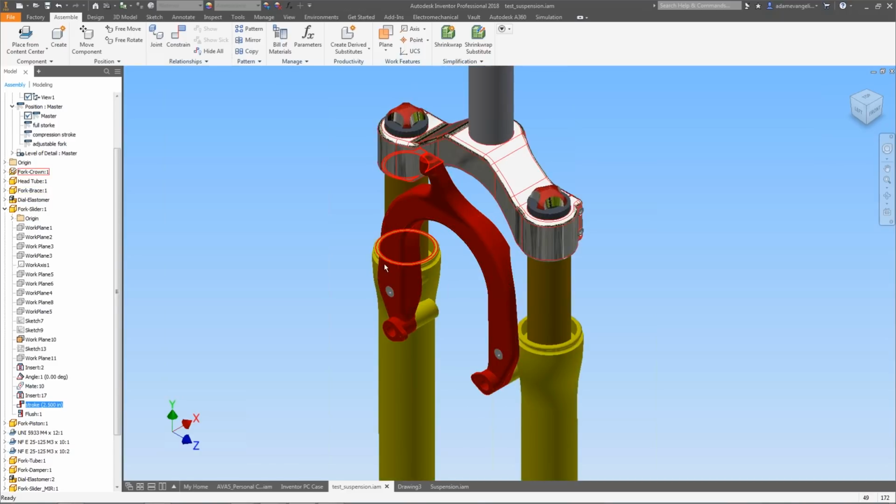If you see these red circles over here, this is the constraint that we're concerned with. By default, in the master representation, that constraint is set to 2.5 inches, right? So if I try to move the model, it's not going to move. It's not going to do anything. You've blocked all degrees of freedom. Exactly. Yeah. So it's good to go. It's constrained as you would expect it to be.